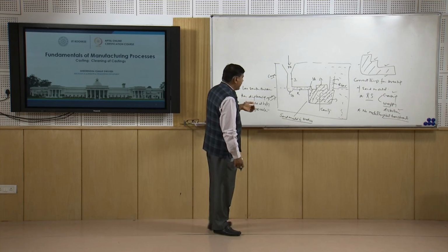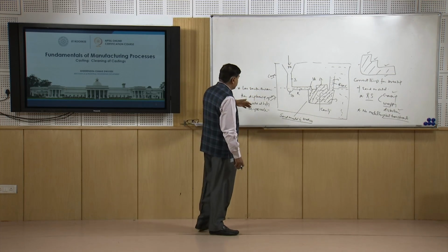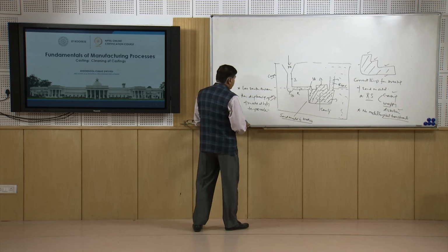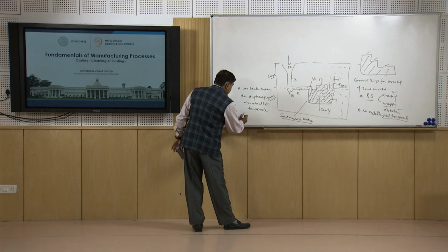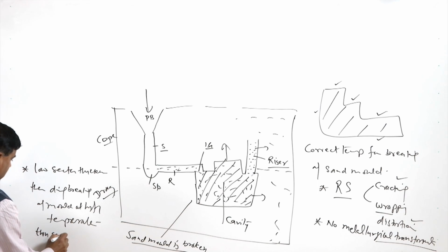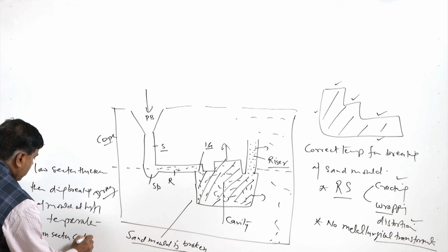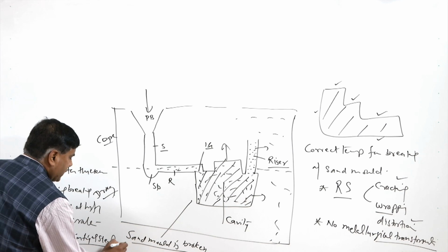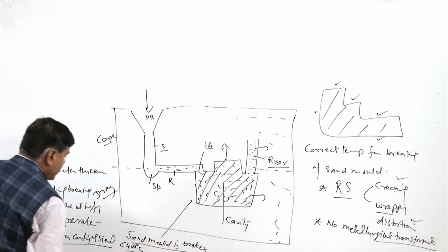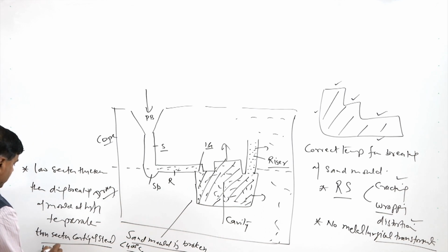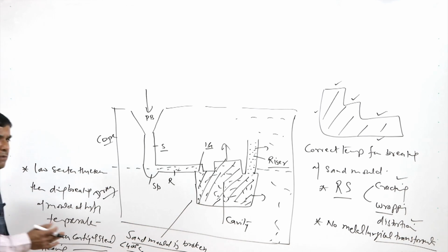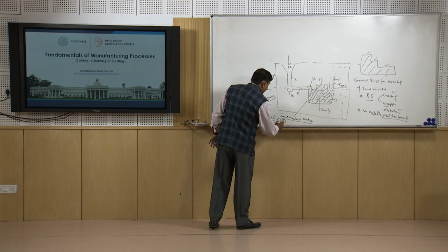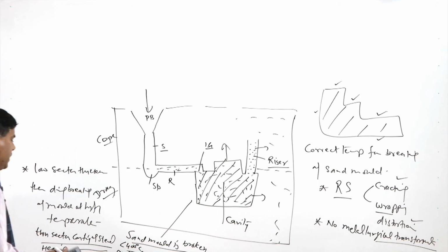That can lead to either undesirable deformation or the fracture of some of the thin segments or thin sections of the casting. For example, thin section castings of steel should be extracted at a temperature below 400 degree centigrade, while if they are of heavy section, this can be done even at a higher temperature, because heavy section casting will not break so easily. So it can be 500 degree centigrade at which these need to be extracted.